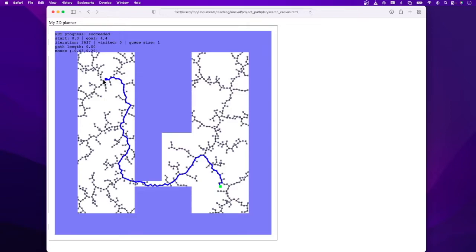And so this motivates a thought that we could potentially improve the efficiency of our algorithm if we used the knowledge about where the goal location was in configuration space to prioritize exploration in that direction. This motivates the creation of what's called the RRT Connect algorithm. This is the next algorithm that we'll be looking at, and it's the actual algorithm that will be required for assignment 6.